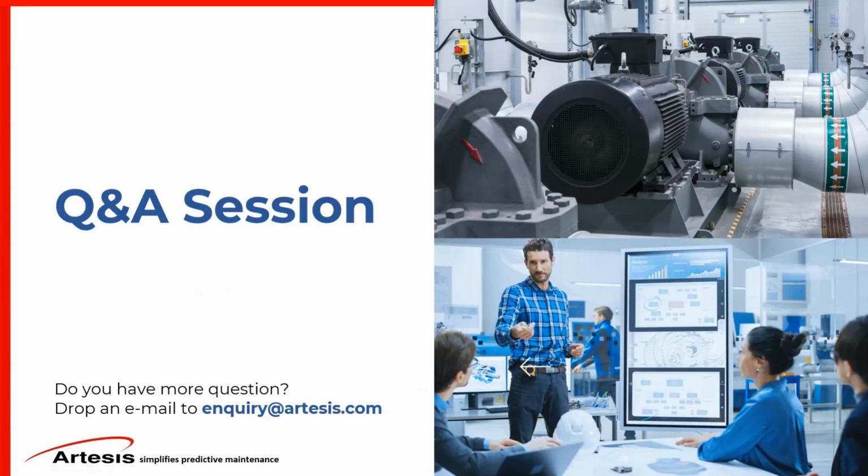Another question: mechanical vibration tools can detect from low speed frequencies to high frequency and detect more than 50 symptoms. Can Artesis cover all the same as vibration tools? As I mentioned, we do low frequency analysis, high resolution, and high frequency. We can see any problems up to 5 kilohertz, and that's probably similar to vibration analysis.